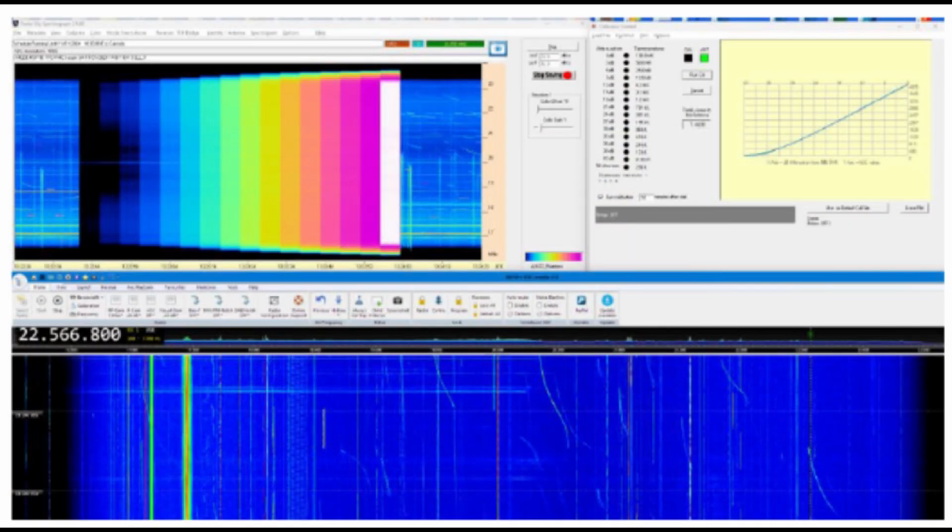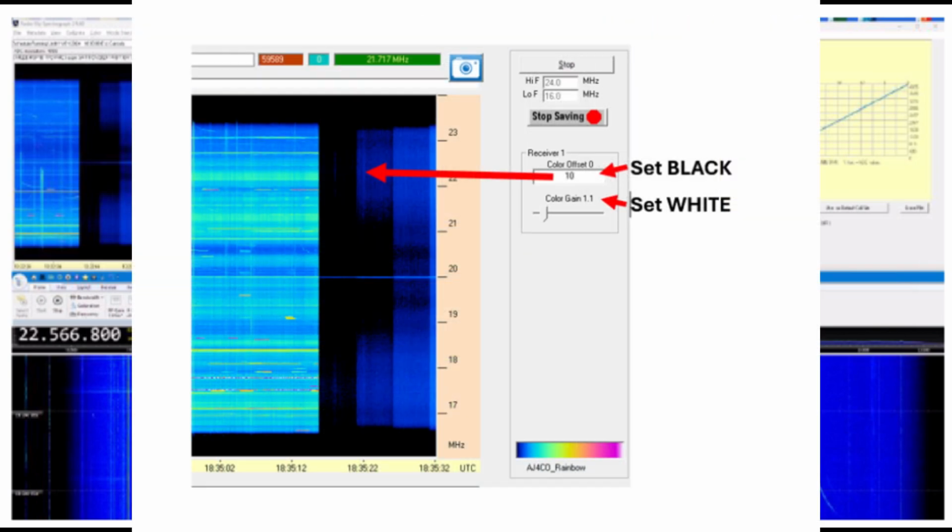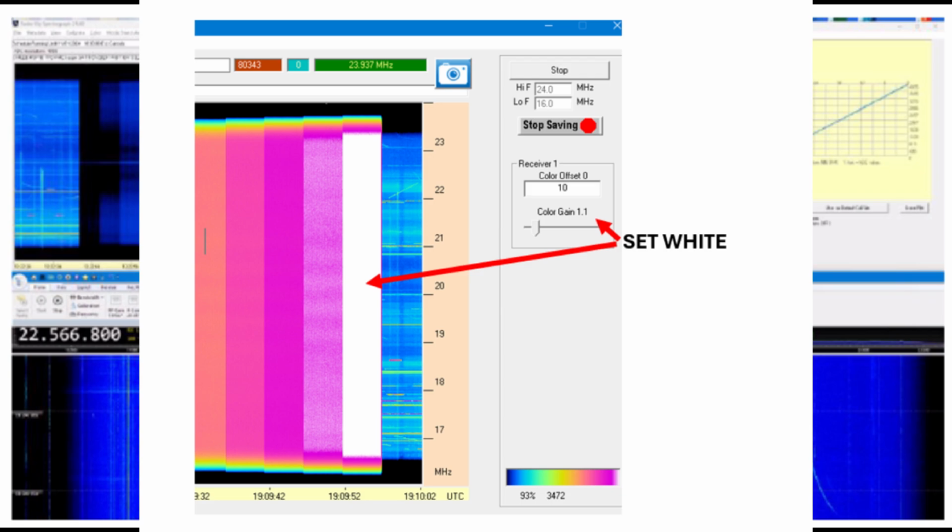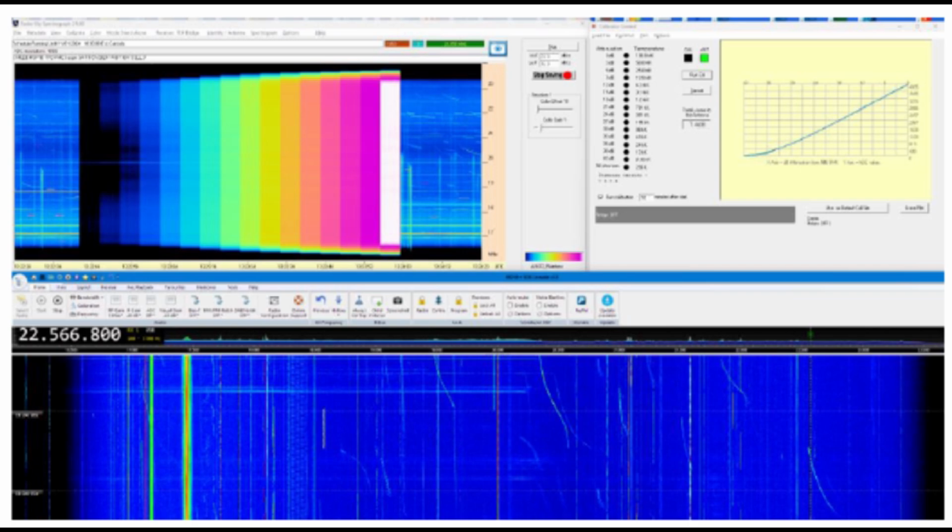Now, you can understand why you cannot use canned settings from a neighbor or anyone else other than for uncalibrated work. Due to the many factors, the station operator must perform an actual calibration with the special Radio JOVE do-it-yourself hardware calibrator. After running the described calibration process, a spectrograph can be designated calibrated to meet or exceed citizen science requirements. Thank you for completing the calibration process for your Radio JOVE Astronomy Observatory.